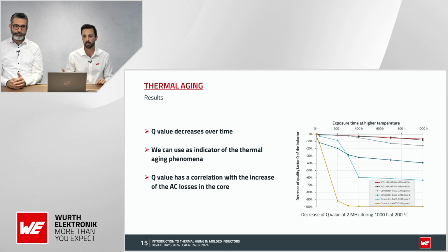So in that case, for example, our part after 1000 hours had a change of 10%. If we want to see the same change at 150 degrees, it means that we would have to wait more than 30,000 hours. It is quite a long time for this testing. It's almost 3 years and a half.